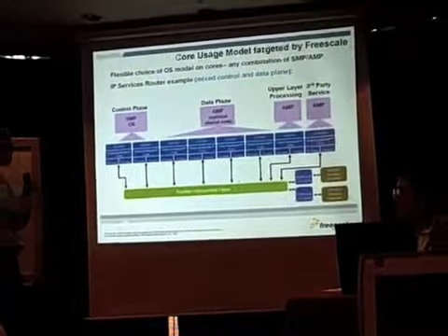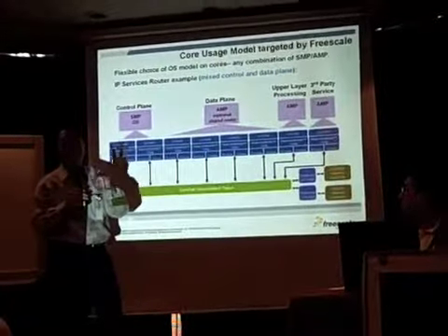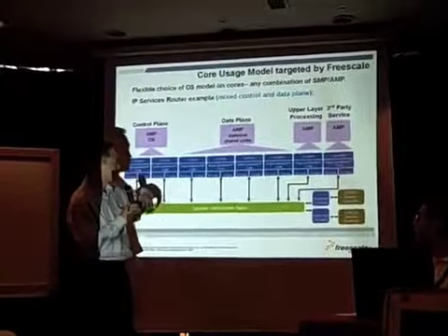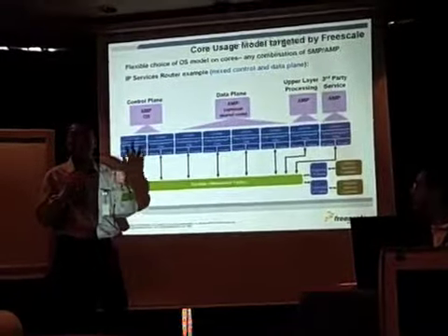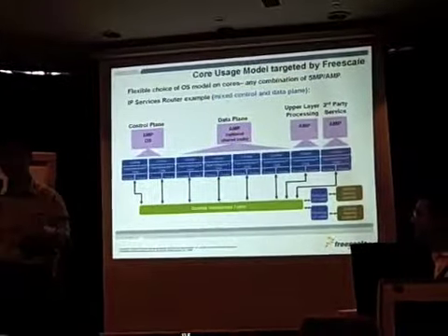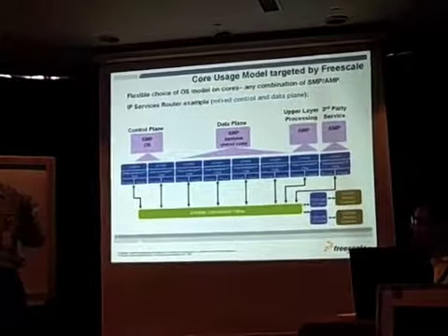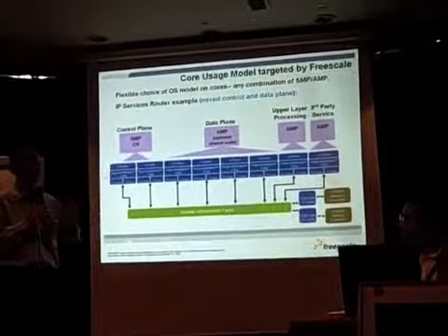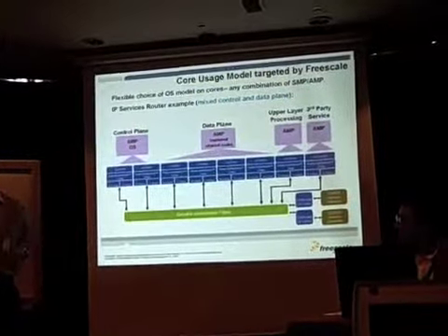A lot of the time, this processor is busy, that one is not, and for the same flow of a networking stream, you may have the first packet go to this device and the next go to that device. Then what happens? They will be out of sequence. So with multi-core from Freescale, we think about that, and we have another queue manager to manage the flow. They can go in out of order, but when they go out to the actual I/O port, they don't go out of sequence.